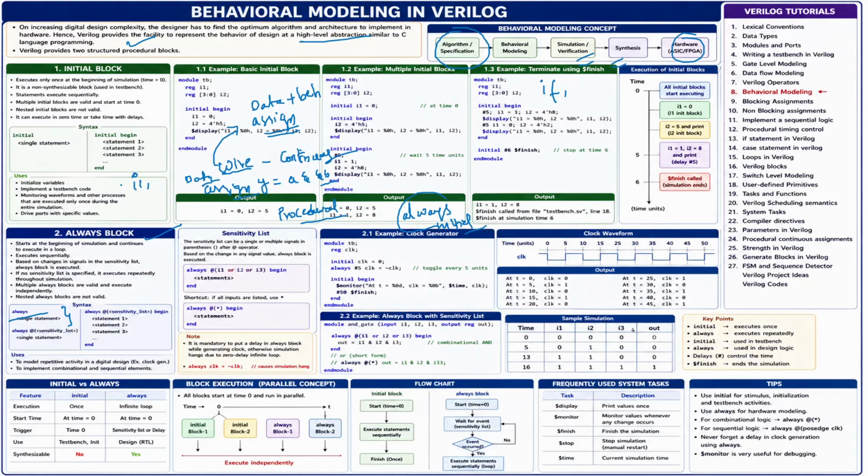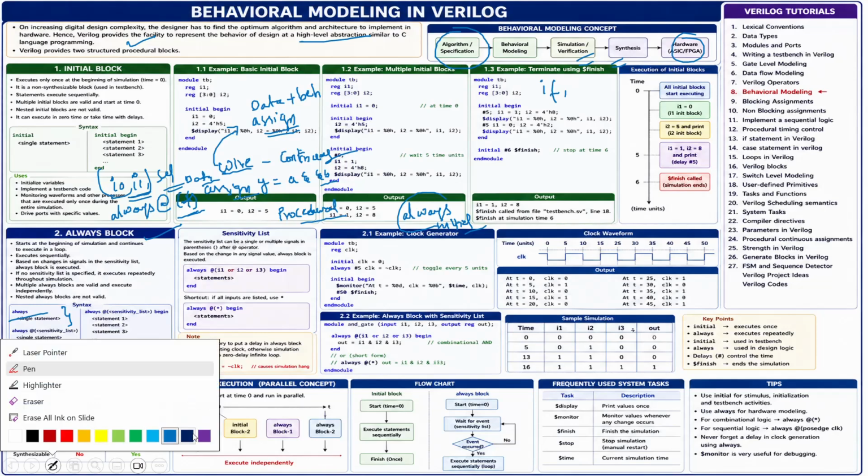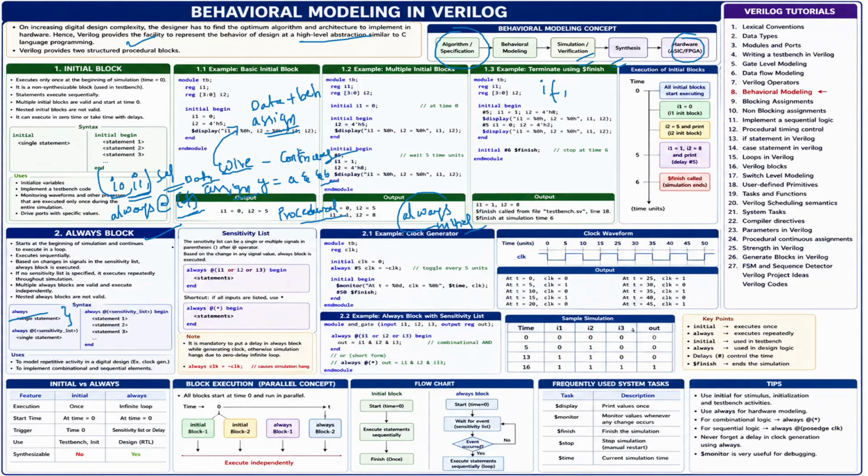Inputs I1 and I0. For this 2 by 1 multiplexer, two inputs are there, and a select line is also there. Any time the select line, I0 or I1 changes, your output will change. So that sensitivity list we need to mention inside the always block. Always at the rate star you can represent it, and that star represents the whole sensitivity list, whatever ports you are using in your design. That is the usage of the always block.